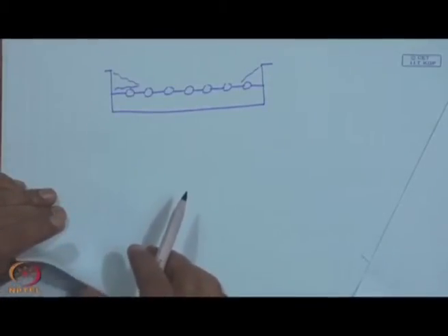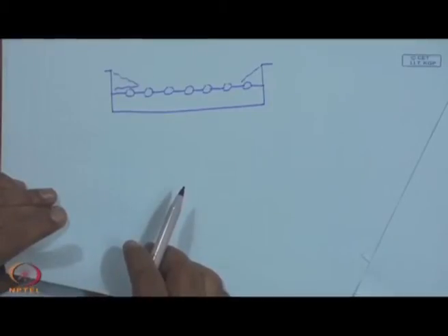So, these are the important assumptions that are made, a number of them. Main thing is steady state performance, though we know that the solar radiation is changing. Secondly, the two-dimensional problem is treated as two one-dimensional problems, and uniform flow is provided to the risers. And in so far as solar radiation is concerned, the glass covers do not absorb the radiation, they are opaque to infrared radiation, and the other common things that we have mentioned.